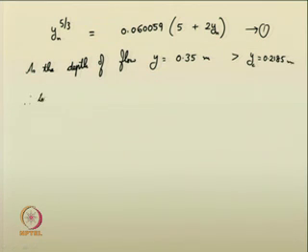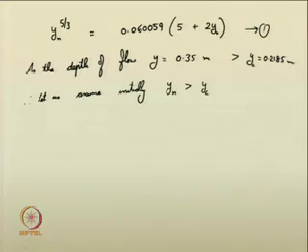Therefore, let us assume initially y n is also greater than y c. Let us consider it as a mild slope initially, because in most of the cases you may observe mild slopes, especially for distribution channels and all.